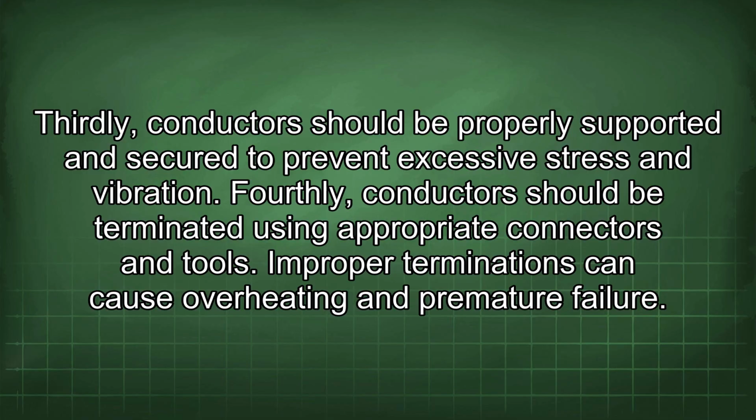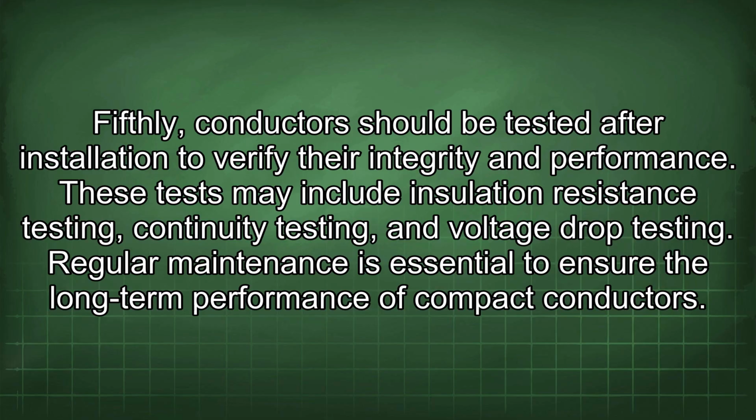Fourthly, conductors should be terminated using appropriate connectors and tools. Improper terminations can cause overheating and premature failure. Fifthly, conductors should be tested after installation to verify their integrity and performance. These tests may include insulation resistance testing, continuity testing, and voltage drop testing.